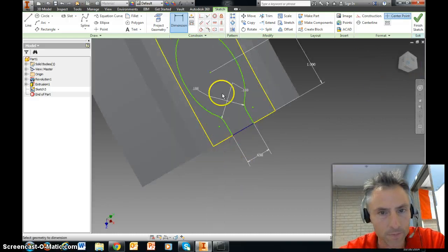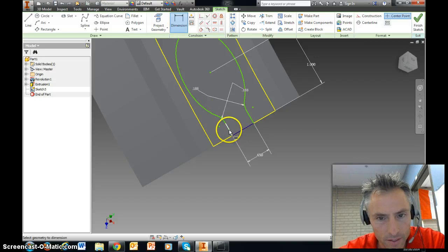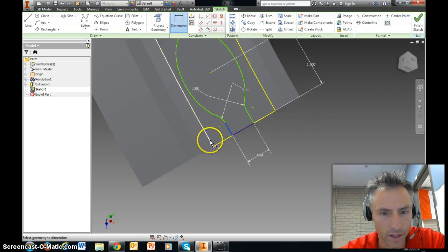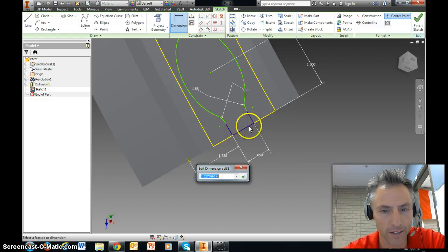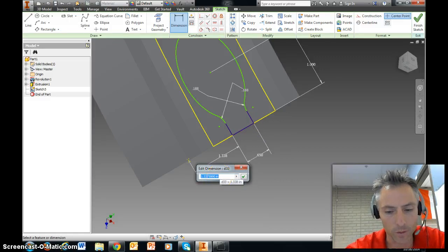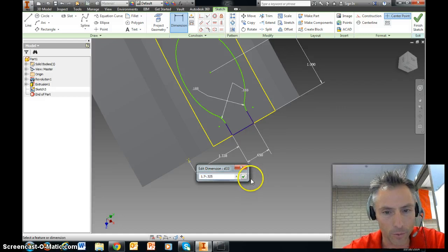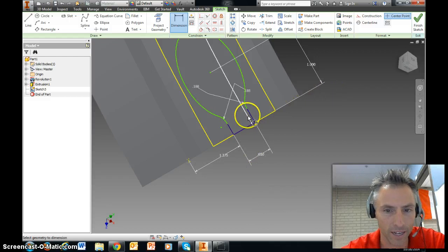We're going to tell this line and this outside edge, okay, halfway would be 1.7, but this is 0.65 wide. So we have to subtract off the half of the 0.65, which is 0.325. So what we really want is 1.7 minus 0.325, and we can put that calculation in there, and when we hit OK, it's going to go ahead and calculate for us. And now it did an adjustment.